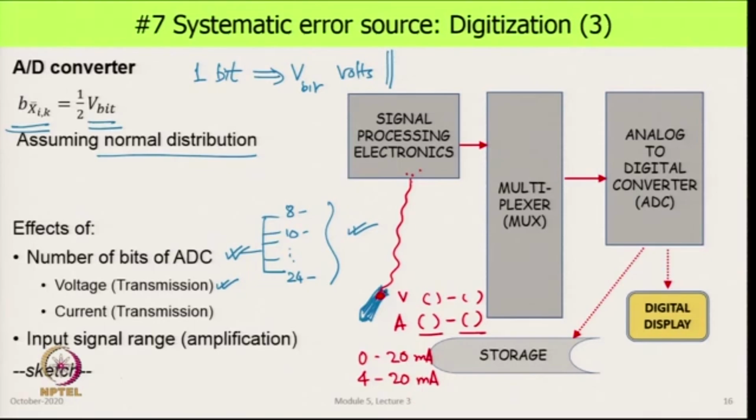And so, what happens is the same current is coming to the processing electronics, where you pass that current over a resistor and you then input the voltage value to the signal processing. In this process, the length of the cable, which is this length here, becomes immaterial, because this current device has been designed for a certain length of the transmission cable.